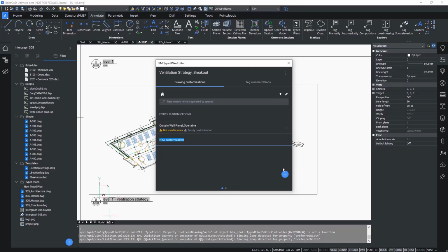We have two main features to highlight, one being openable curtain walls and the other naturally ventilated spaces. We will also include others, which I would like to dim down so my main graphics stand out in this diagram. Now, we can determine the color palette scheme. So let's go on to styles. I'm going to make this strategy with tones of blue. So I'm going to first specify a BricsCAD logo blue and a light blue. I'll add a light gray in.